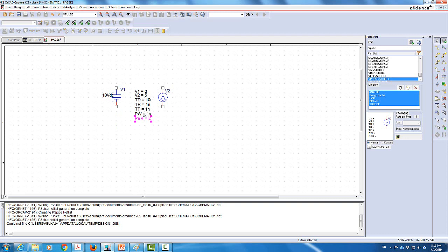We will run it around 10 times tau. In this case, we can run it up to like 20 microseconds. That's more than 10 times tau. That's like 15 times tau, because tau was 1.14 microseconds. So it will never reach the end of the pulse width. So we will never see the square wave.